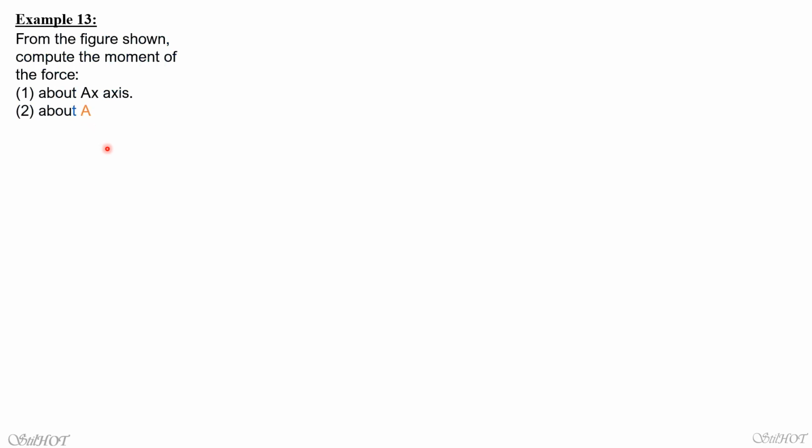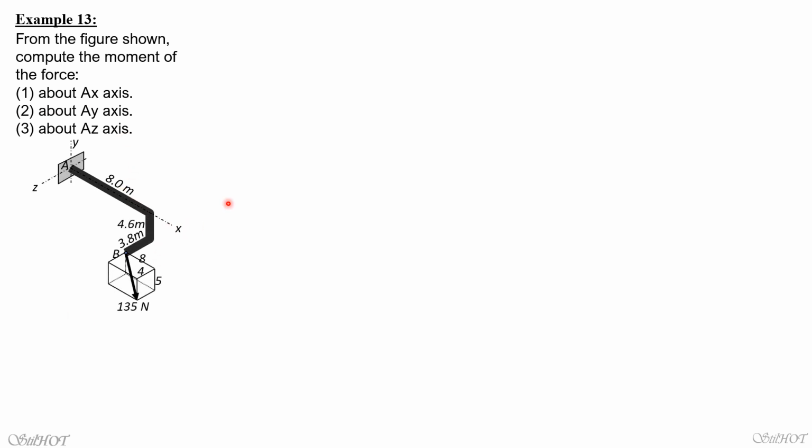Okay, let's solve sample 30. From the figure shown, compute the following: number 1, the moment about the AX axis, number 2, the moment about the AY axis, and number 3, the moment about the AZ axis. So this is the figure. Let's solve this by the scalar approach first.